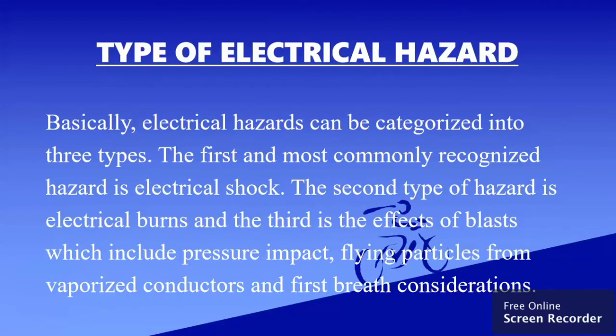Types of electrical hazard. Basically, there are three types of electrical hazards. The first and most commonly recognized hazard is electrical shock. The second type of hazard is electrical burns, and the third is the effects of blast, which include pressure impact of flying particles from vaporized conductors and fumes or breath considerations.